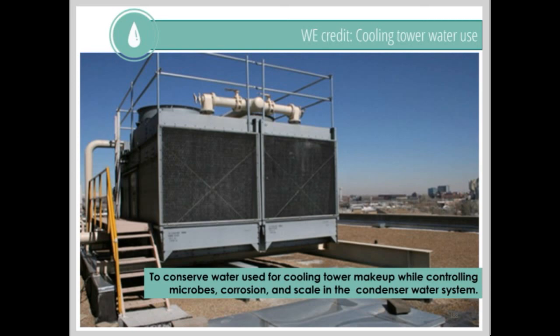Cycles can also be increased by treating water to remove or sequester dissolved solids rather than relying only on blowdown and input of fresh water makeup.